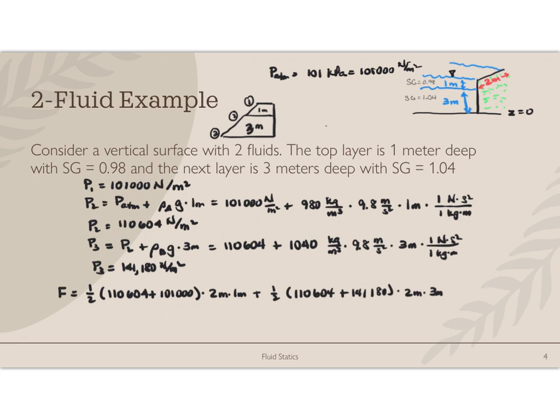The units here were newtons per square meter times square meters, so this is all going to be in newtons. The force, therefore, is 211,604 newtons plus 755,352 newtons, or 966.956 kilonewtons. Probably that's ridiculous sig figs, and I would go with 967 kilonewtons.